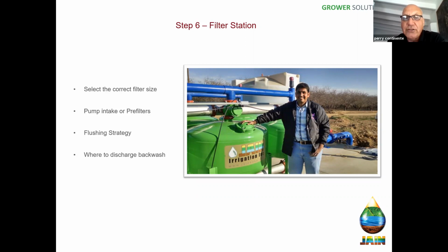And what I just described as the flushing strategy: are we going to use a pressure sustaining valve, or are we going to provide a VFD, which means it'll provide the additional flow and pressure only when we need it? That's my strong recommendation, has been with a variable frequency drive. And most people are extremely happy with them when they get them and they understand how they work and how it works for them.